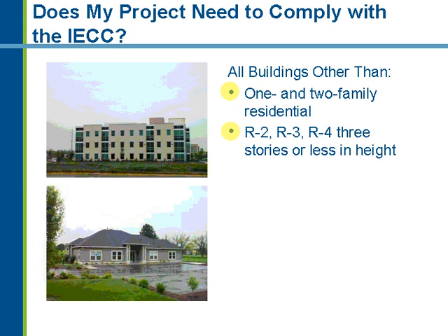So from a commercial standpoint, this is going to cover what was covered underneath the 2003 code, including offices, retail, hotel, motel, assisted living with greater than 16 occupants, and essentially any building greater than 3 stories. The 3 stories is an important point because a 4-story condominium building would be considered a commercial building. A 4-story condominium with an additional floor of retail is all still considered commercial occupancy. So you really have to pay attention to the number of floors in the building and the occupancies that are within that building.